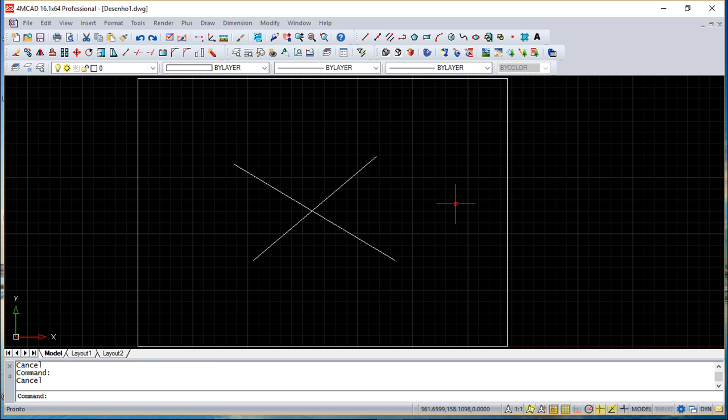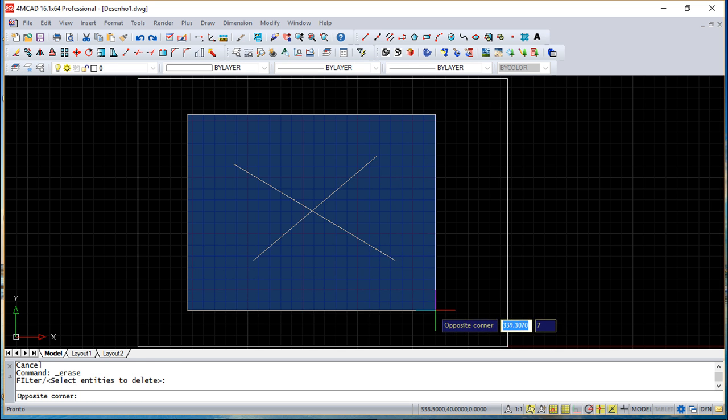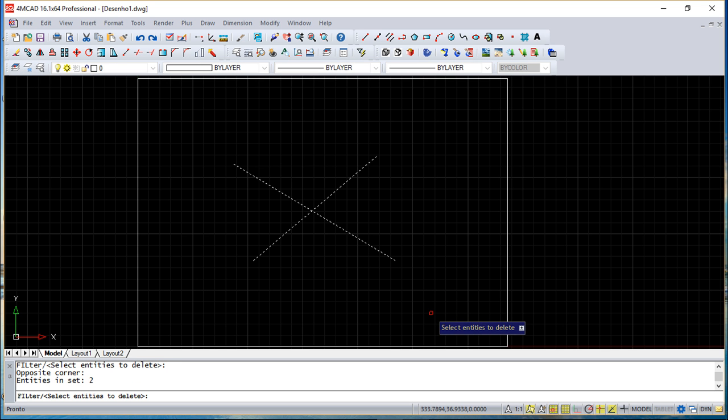One very interesting and important option also is that when you select a pack of entities and then you realize that there is one or more entities that you need to deselect to take out of this package, then you click on the shift and you can click on top of the entity or open a window, and then they change their status from this dashed state that says selected to this continuous one which is not selected.